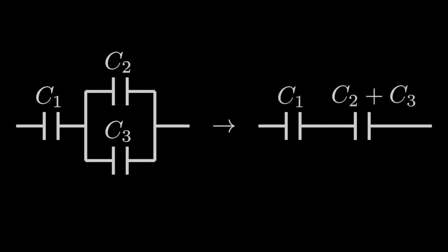Now moving on, do we have any branches in parallel here? We don't, because there is no branching off anymore. In that case, do we have any components in series? All we have left are these two components, so if we trace our finger along the path between them, there's no branching off between them, which means these two components here are in series.